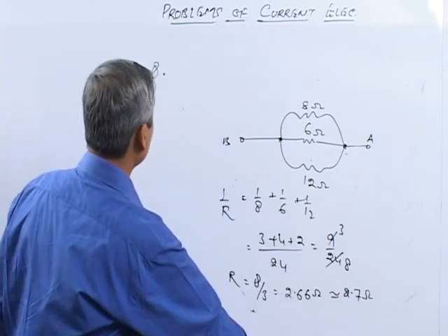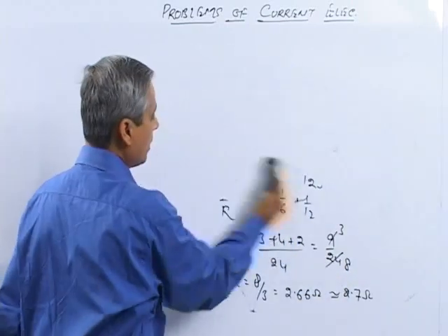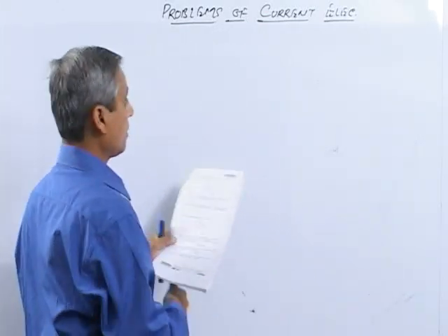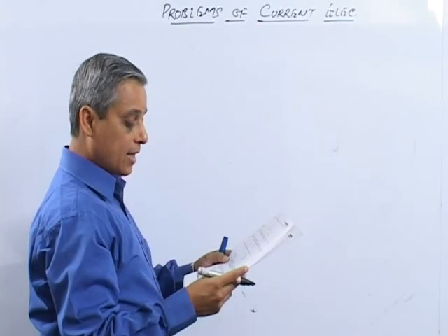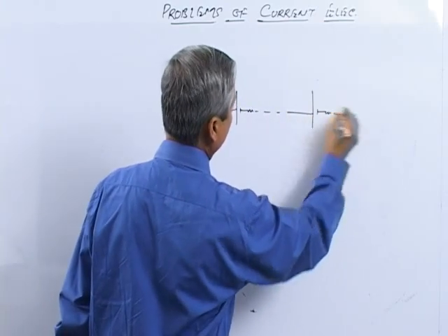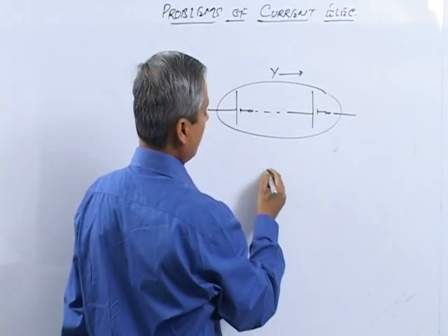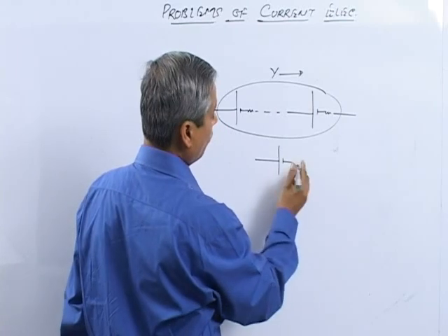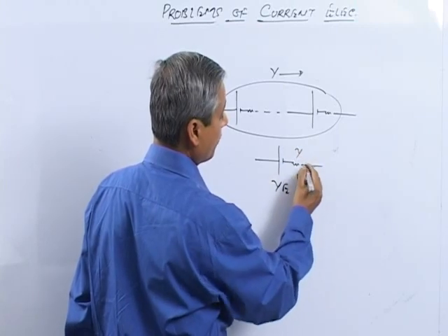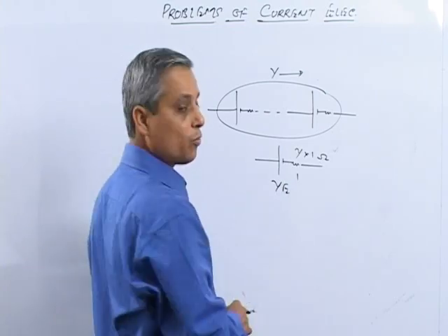Now here we are trying to make a battery which is made of a combination of 8 cells. Now, if there are Y cells in series, you will have cells connected like this, Y cells in series. So each series combination will behave like a single cell whose EMF will become YE and internal resistance will become Y into 1 ohm, because each battery has an internal resistance of 1 ohm.